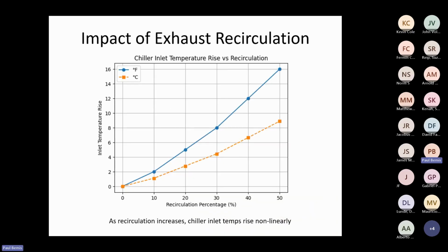And those issues look like this. What happens is they recirculate. The chiller, I'll show you in a detailed example, starts to recirculate on itself. The air wraps around and the exhaust air gets drawn back into the intake air and performance declines. So this is a derating chart that says, as inlet temperature rises, as recirculation percentage increases, so the amount recirculating from exhaust to intake goes up, the performance of that device goes down.